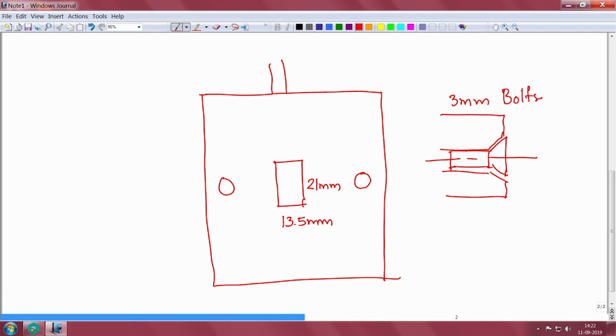So, this whole dimension is 3 mm and the bolt diameter will be a little less than 3 mm, and we will be 3D printing an enclosure. So, we have to take care of the tolerances. We can give a 0.5 mm decreased dimension to the hole. That means the hole dimension will be 2.5 mm, so that we can directly screw this bolt into the hole and everything will sit together easily.